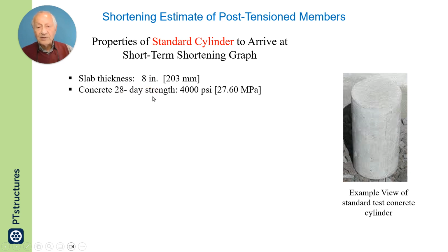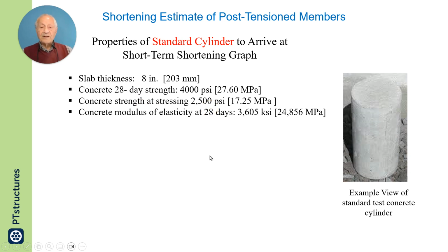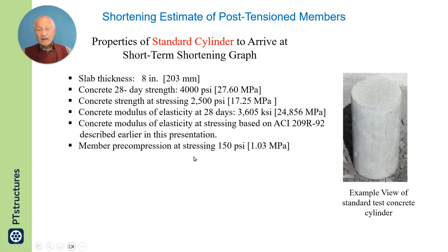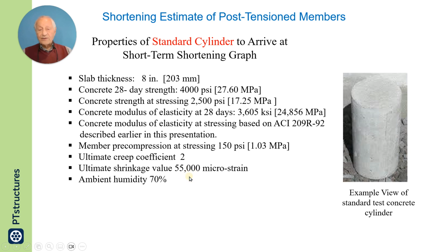Your condition might be a little bit different for a given slab thickness, concrete strength, and stressing at a given concrete strength, modulus of elasticity, pre-compression of 150 psi, assumed creep coefficient and shrinkage values, ambient humidity, and so on.